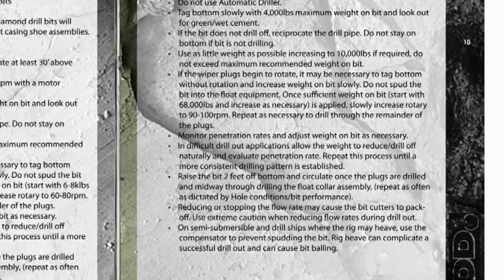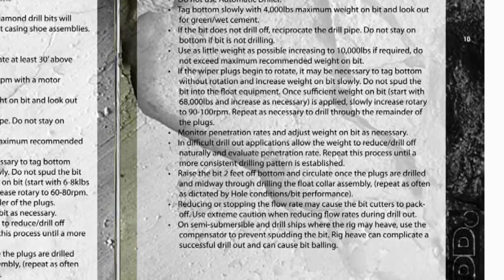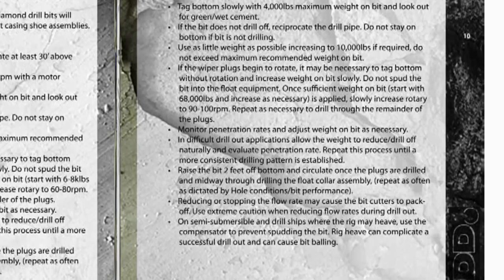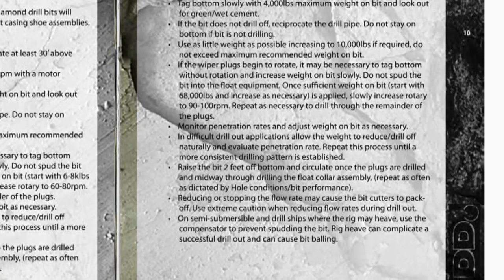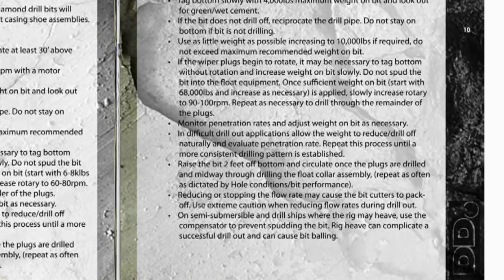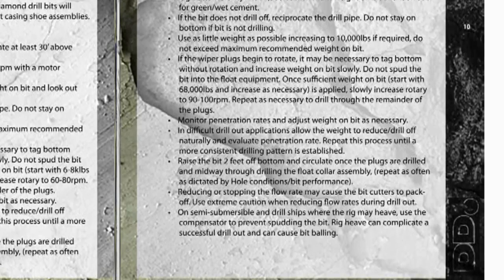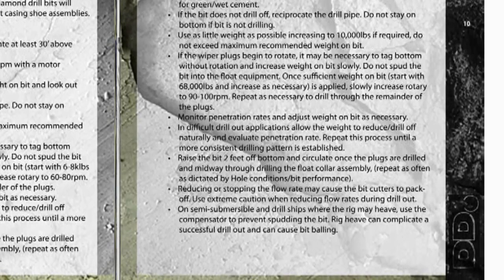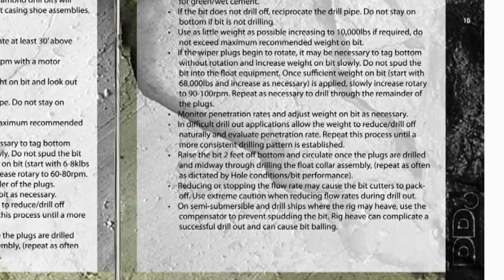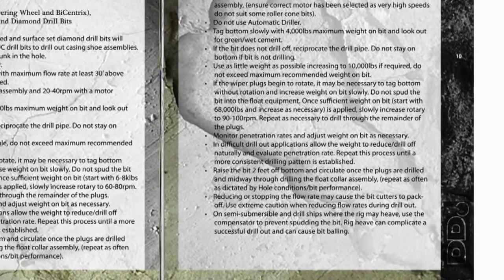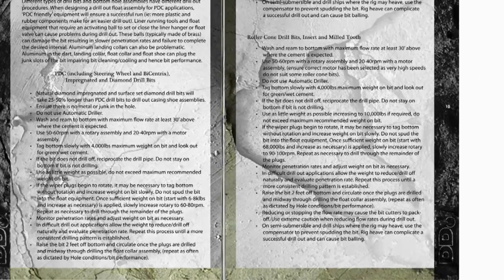Reducing or stopping the flow rate may cause the bit cutters to pack off. Use extreme caution when reducing flow rates during drill-out. On semi-submersible and drill ships where the rig may heave, use the compensator to prevent spudding the bit. Rig heave can complicate a successful drill-out and can cause bit balling.